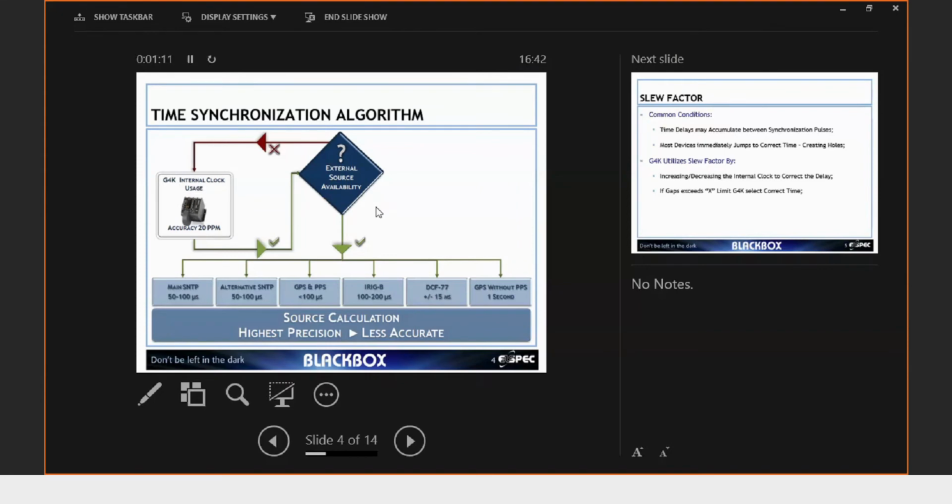Now, let's say you are using a GPS antenna and there is a big storm and the skies are cloudy and there is no signal. So let's say after 5 or 6 hours, the skies get clear, so the unit will capture the correct time. In 5 hours, you will have approximately 300 milliseconds offset. After those 5 hours, it will correct to the correct time. This is for GPS. Of course, for SNTP, you do not consider sky view.